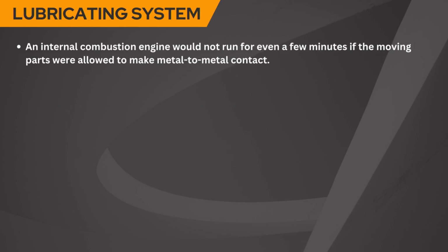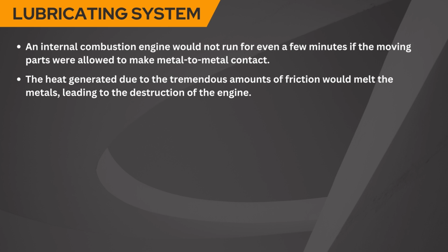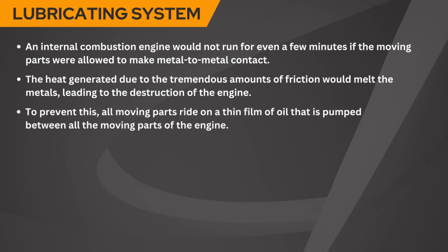So, the oil coolers incorporated in the system generally keep the temperature of the oil low. Generally, in internal combustion engine, it would not run for even a few minutes if the moving parts were allowed to make metal to metal contact. That's why lubrication is very important. Also, the heat generated due to the tremendous amount of friction would melt the metals and which would also lead to the destruction of the engine. And to prevent this, all moving parts ride on a thin film of oil that is pumped between all the moving components of the engine.